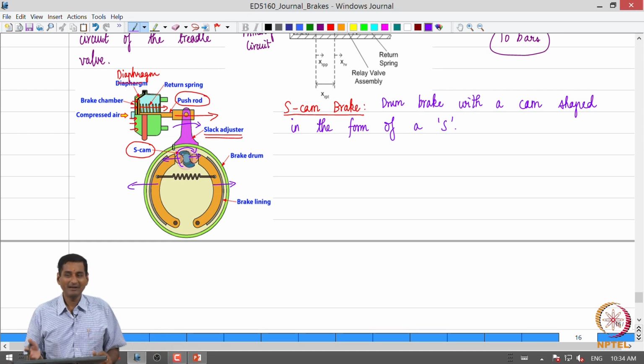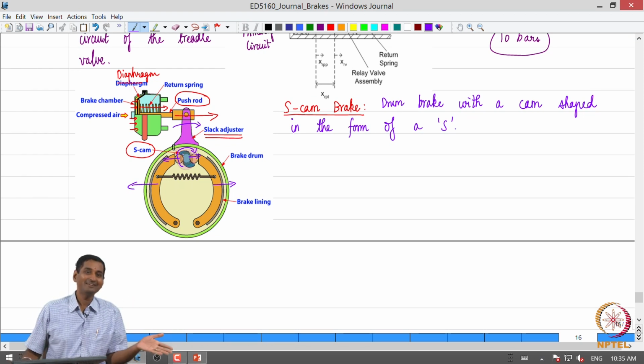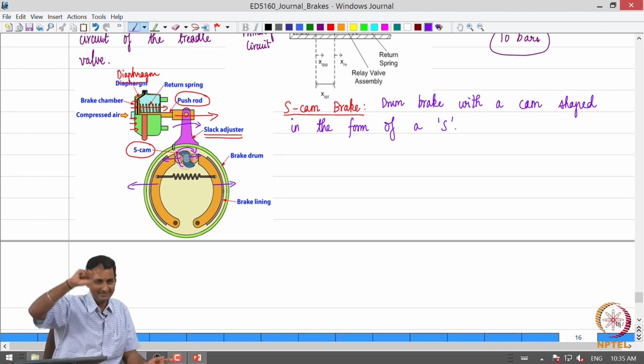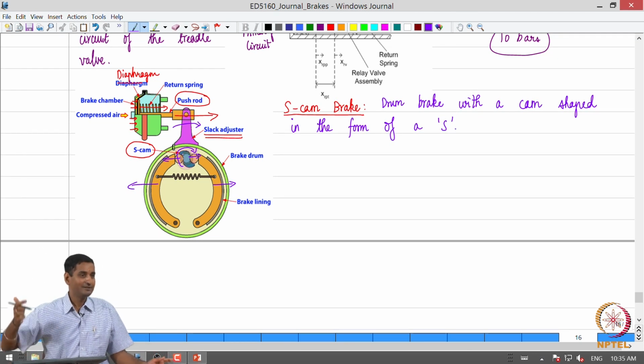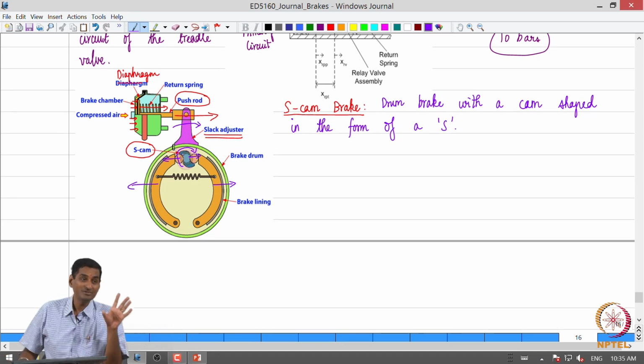See, this is our maximum, of the order of 10. In a hydraulic brake system, the brake pressures can go up to the order of 10 power 2 bars, right. So, you can see that the maximum operating pressure in an air brake itself is one order of magnitude lower than that of a hydraulic brake. In fact, we would have wanted the other way, right. So, you can see that now I have a huge deficit, because the actuating pressure is smaller than that of a hydraulic brake. Then how do I generate higher actuating force?